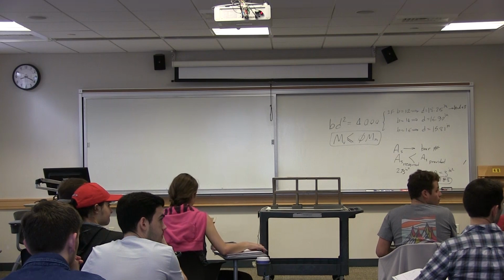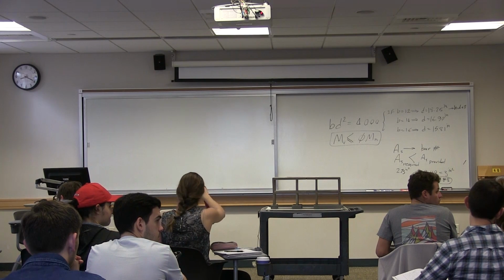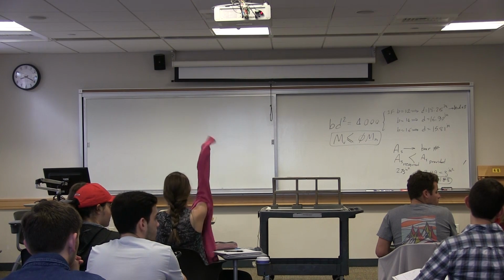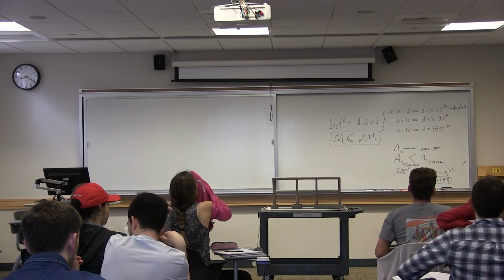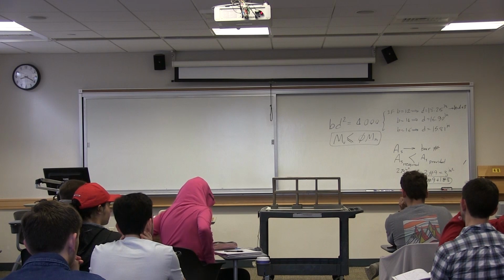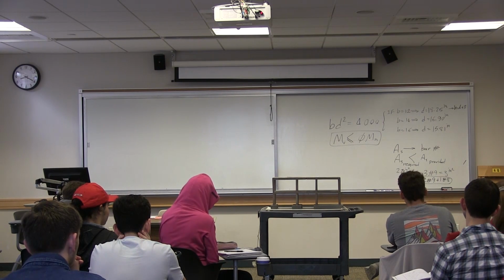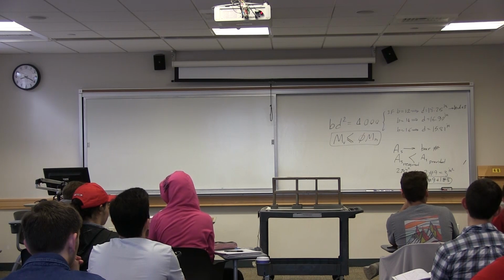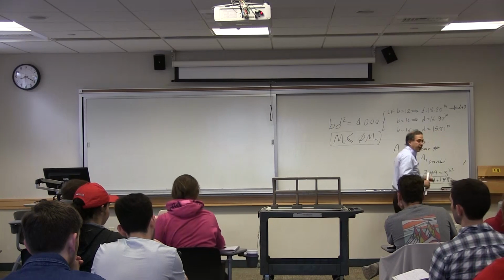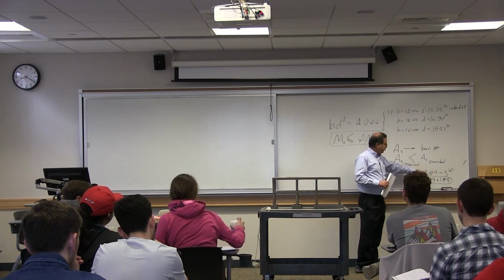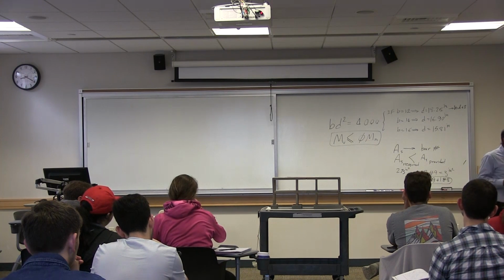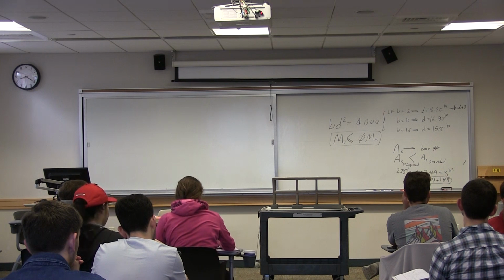So you've answered most of it. It makes sense. But what indicator will we know we need to go change something? If the weight was not approximated, there is nothing to check. But if it was approximated? That's a different story. I'll explain that. But if your solution is exact, your numbers are exact, there is nothing to check. Nonetheless, it's always a good idea, after you found the rebars, to calculate Mn one more time just for verification, just to make sure that you didn't make any mistakes.